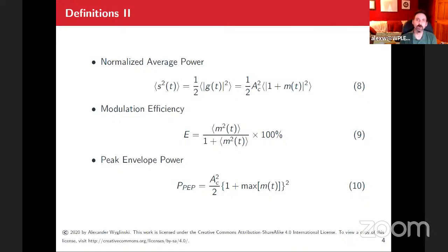And likewise, what we saw earlier, in terms of detectors, recovering that message signal M of t is also relatively easy. We pass it through a square law device, take the output, and low pass filter it to extract just the baseband component, which will be G of M of t squared. Then we take the square root of that to get G M of t. Then we divide by AC and subtract off the bias to get M of t back. All right. So that concludes lecture 15 of ECE 3311.